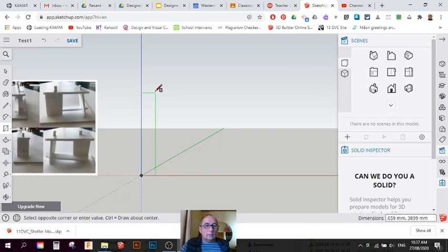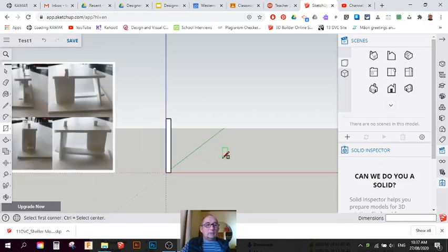So first of all, first wall. It's going to be 200 mils by 2200. Right, and there's my first wall. It's looking quite thick. Okay, undo that. Let's make it again. This time, oh, not from the center. That's interesting. That's better. So let's say 150 by 2200. There we go. That looks a bit more realistic. Good. So now I've got that part.